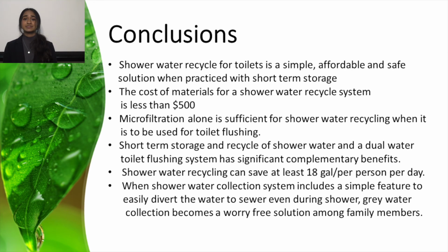My research proves that shower water recycling for toilet flushing is a simple, affordable, and safe solution, particularly when the tank is emptied approximately every 48 hours. The total cost of my system is less than $500. My research also confirms that microfiltration alone is sufficient for recycling shower water for toilet flushing.